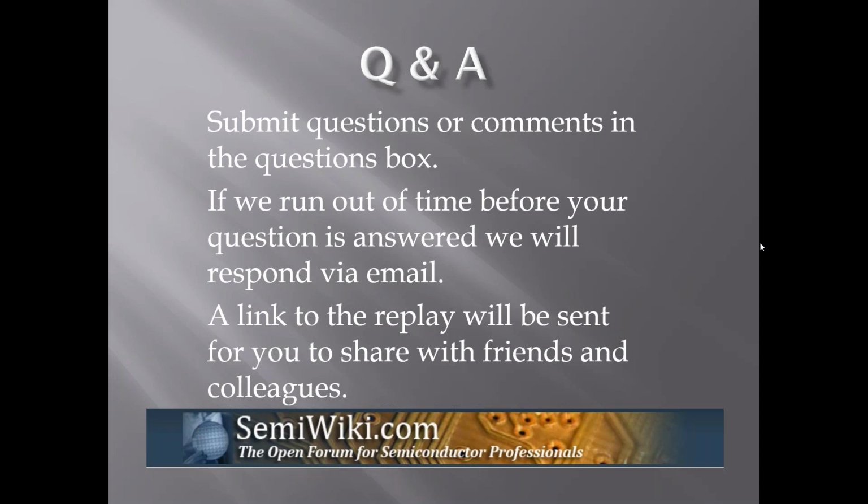Another question. How is ALPS-GT integrated into a Mentor and Cadence tool chain? ALPS-GT, like ALPS, can be easily integrated into the mainstream design environments. You just click a few buttons, then the engine simulator will be swapped from your original simulator to our own simulator, and everything else stays the same. Is it integrated in Virtuoso ADE XL? Yes, it has the capabilities. Just click a few buttons, and the engine will be swapped to ALPS-GT.